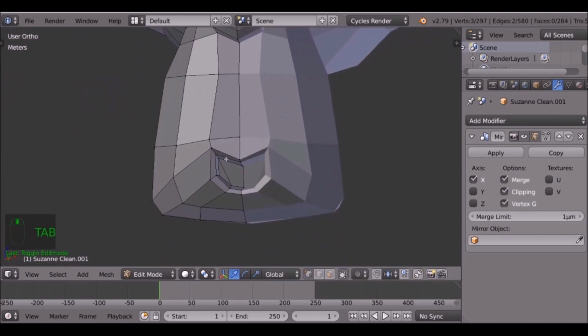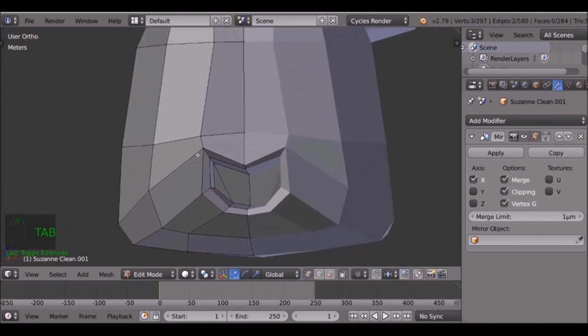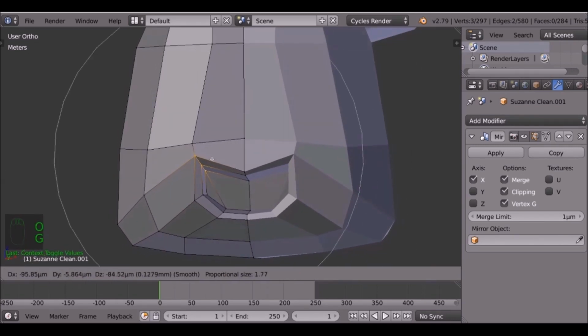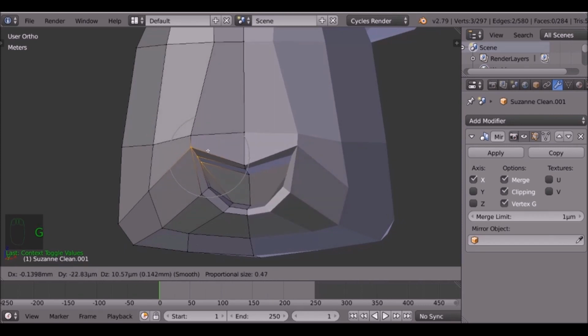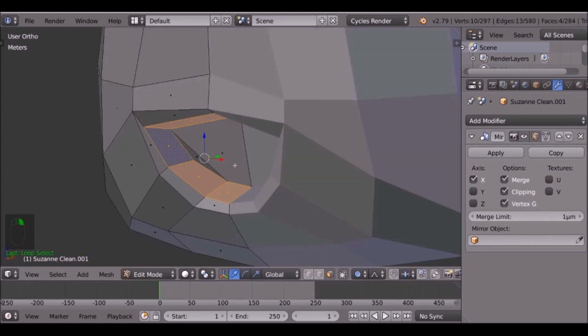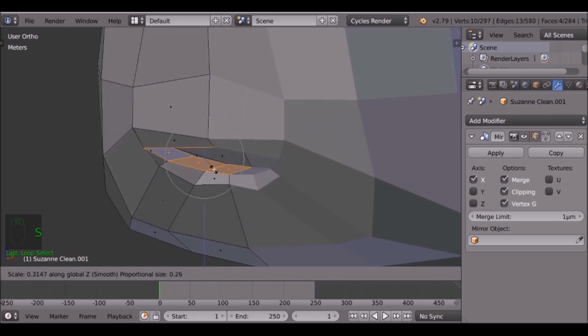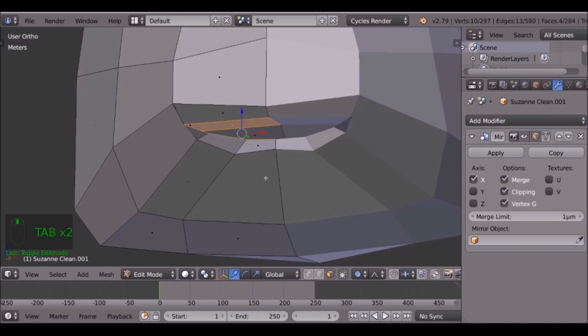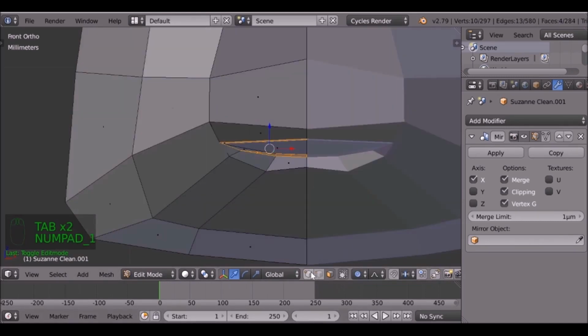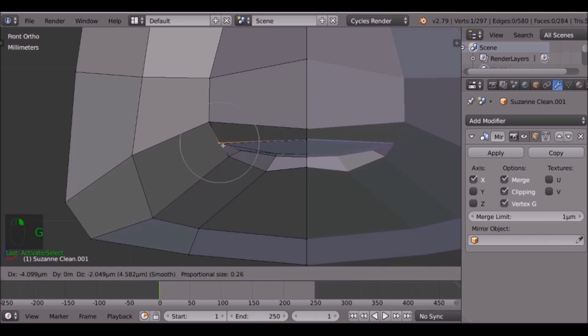And then also change the mouth. I'm going to do the same thing as before, but this time maybe go in the opposite direction. Turn on proportional editing to help make sure we rescale that. Select all of these, press S, Z, just scale this down, and then let's turn him into a sad face. So let's do that now.